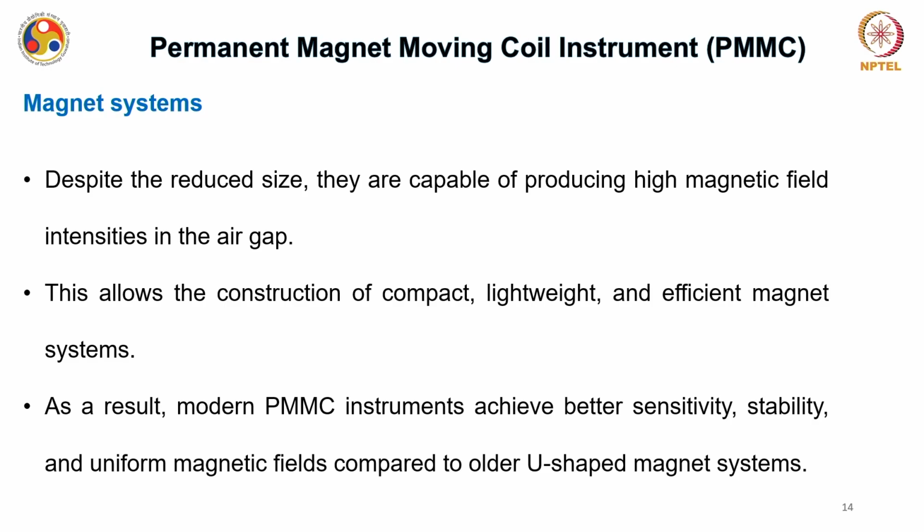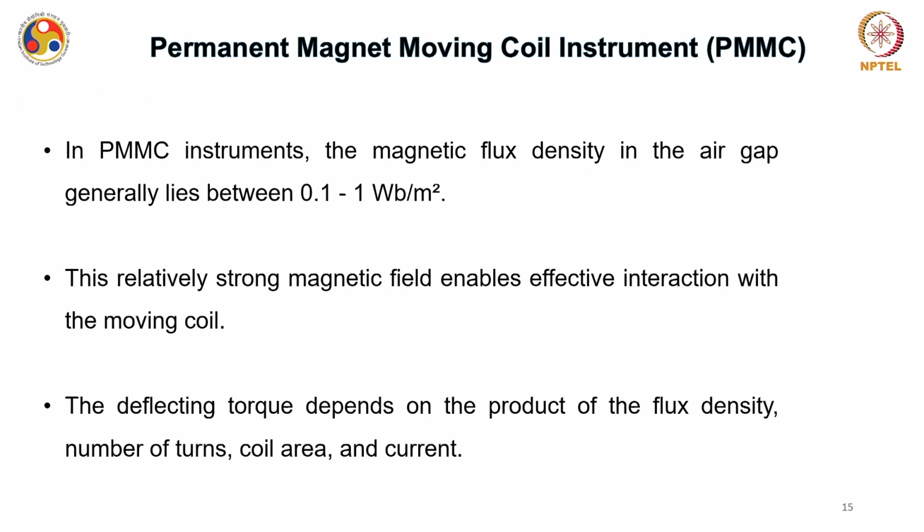Now when you have very high magnetic field intensity in the air gap, this will allow you to construct a compact, lightweight and efficient magnetic system for this kind of tool. Therefore the modern PMMC instrument can achieve better sensitivity, better stability and uniform magnetic fields compared to the old generation U-shaped permanent magnets.